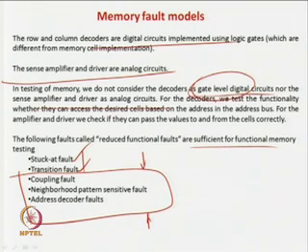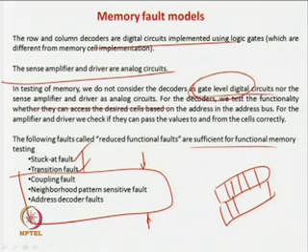This is because the memory cells are like this, and they are very much stacked near each other. So, if you stack these cells of a memory very near each other, what may happen is these two cells may get coupled. So, any changes here may affect here.